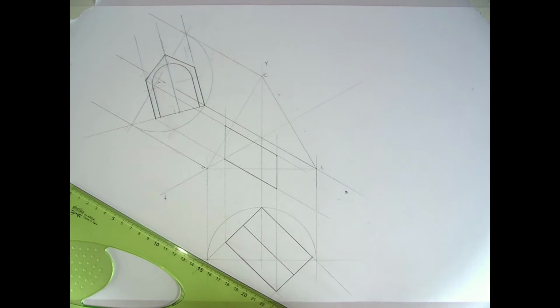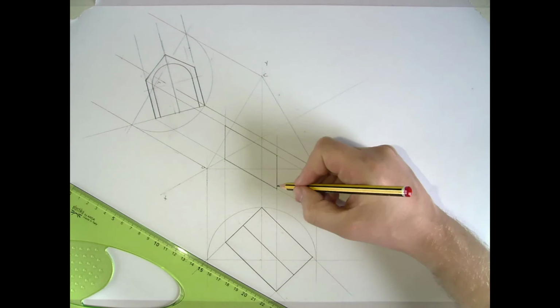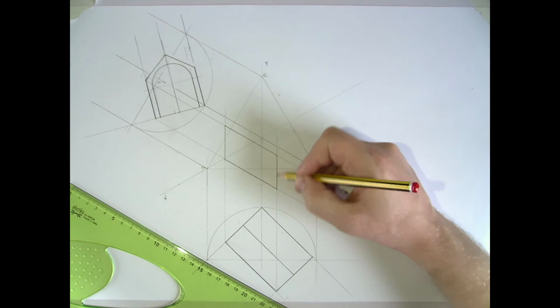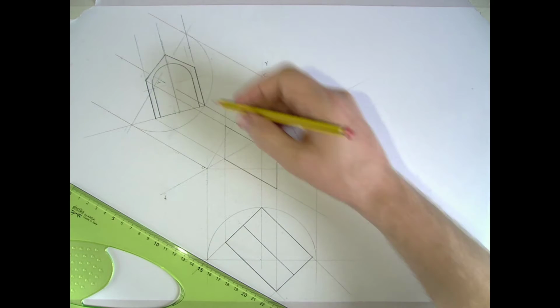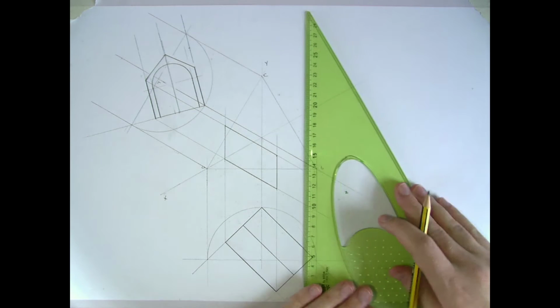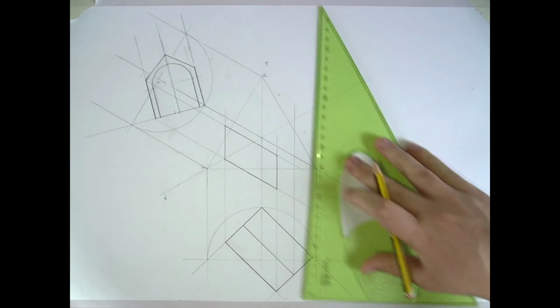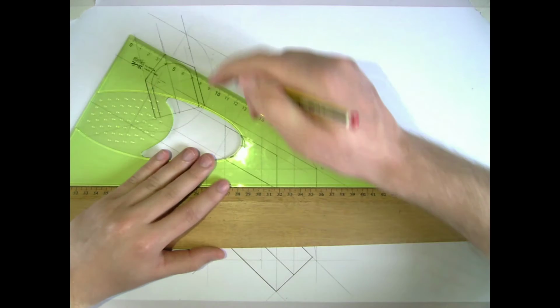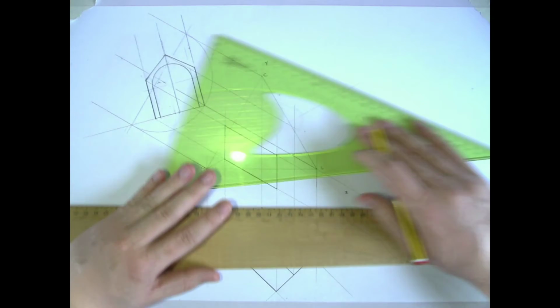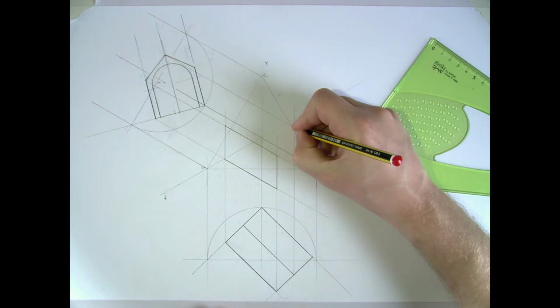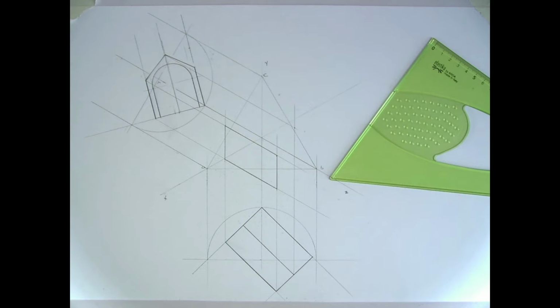Now I'm going to draw the front face of this, and to draw the front face of it I'm going to be taking 1, 2, 3 points. I already have one line of them, so I have this point and this point, so I need to locate the one at the bottom here, this one, and the apex. So I'm going to start with the apex, so this line is projected vertically up. This is the top of the roof, the ridge line, so that's going to be projected down from the elevation also. Where they intersect, that gives me the apex, or the start of the ridge in the axonometric view.